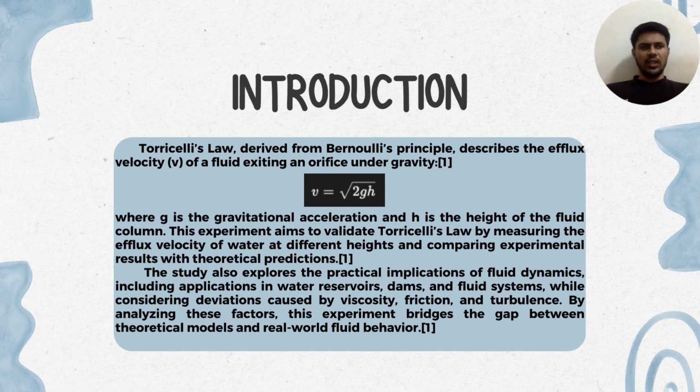For the introduction, Torricelli's law, derived from Bernoulli's principle, describes the flux velocity of a fluid exiting an orifice under gravity, where g is the gravitational acceleration and h is the height of the fluid column. This experiment aims to validate Torricelli's law by measuring the flux velocity of water at different heights and comparing experimental